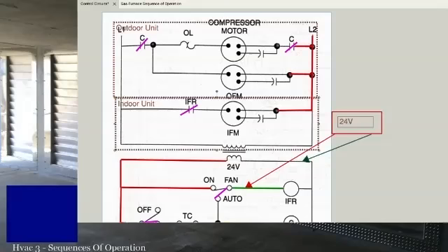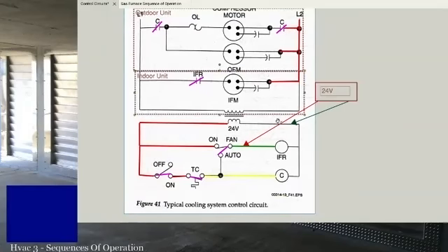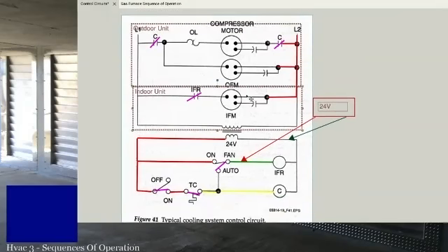So that's why I like to start with sequences of operation, because as you get good at troubleshooting, looking at wiring diagrams and understanding your sequence while you're looking at the wiring diagram can help tell you what to look at when and why. And then you can get faster at sorting out odd problems, or something where you just don't see all the components immediately. You can say, okay, well, I know I've got this, I know I've got that. So what's the actual problem here?